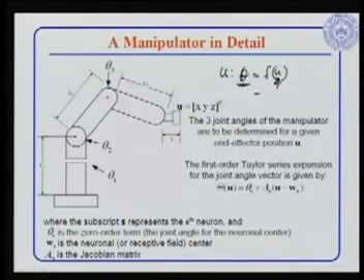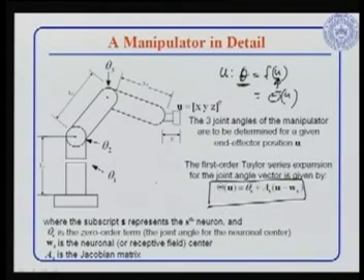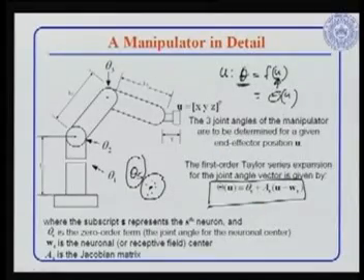So, what I have written here, f of u, is a function of u in this case. Locally it can be linearized around a specific point, as this particular formula, which is in a local zone. If I know theta s corresponds to this point in the Cartesian space, then any point near to this Cartesian point will also be very close to theta s. Thus, we can find this relationship by simply linearizing this nonlinear function around theta s.